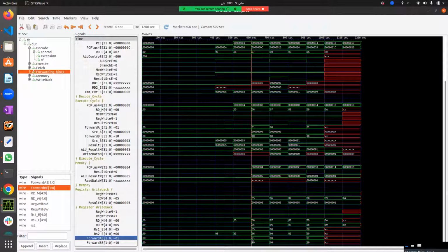So our condition was getting through that we have a RegWriteM, we have an RDM which is not equal to 0, and RDM was equal to RS2. That's why we have a forward A signal of 0, 1. Similarly, you can see that for RegWriteW we have 1 and we have 6, and we are getting from RS2 or RDW, and similarly with RS1. That's why we get 0, 1 and 1, 0. So definitely you can confirm this logic from your side as well individually.